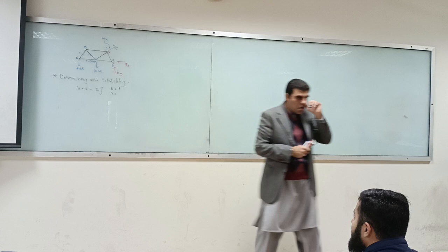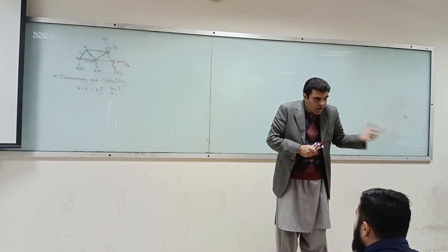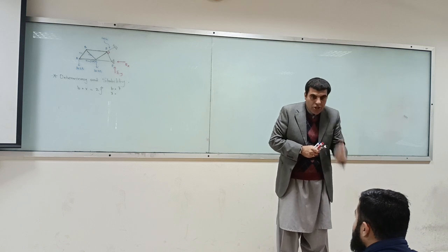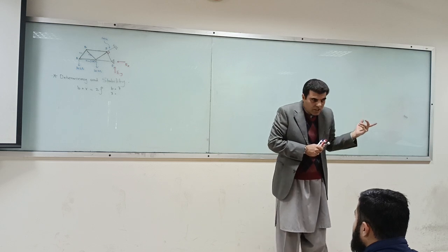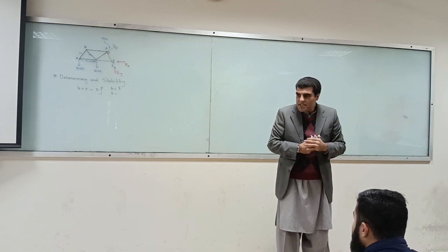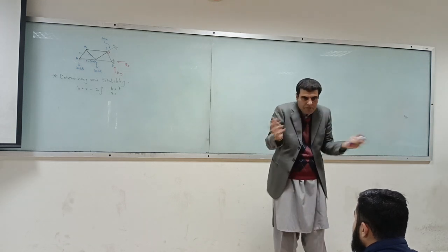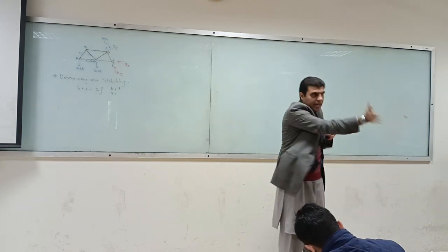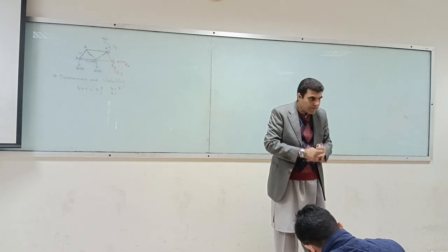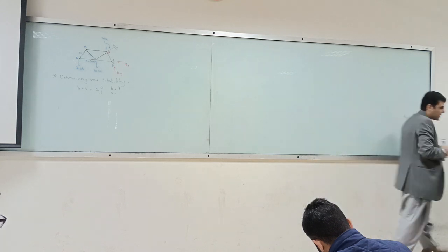You can divide it into infinite components. So what? How many equations do you need to solve that? You can take it in infinite directions. That is not a concern. What is the main equation you require? That is summation of force in the direction of application of force must be equal to 0. That's one equation you need. So you can find the component in infinite directions. That's up to you. If I give you any angle, you can find the inclination. Okay? Is that okay?